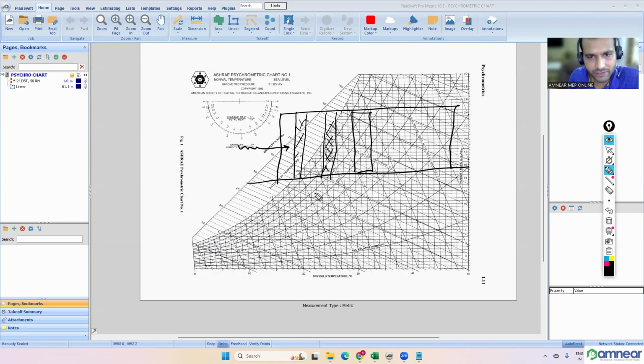So if it is coil based, or a desiccant wheel, hybrid type, combined systems can also come. The air will be entering, then the desiccant wheel will be removing the required water, and after that it will reach the cooling coil. We will have a fan, and then other filters will also come. That is conditional, and anyhow I am not going to explain all those things.